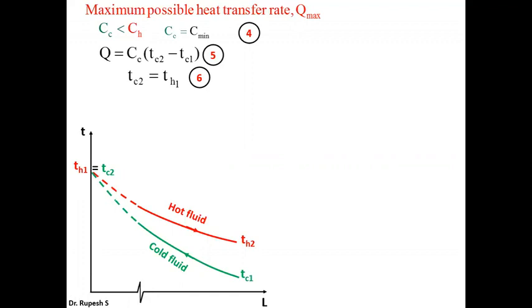So, for maximum heat transfer rate, that is for a heat exchanger with the infinite length, Q becomes Qmax when Tc2 becomes Th1. So maximum heat transfer rate can be represented as Qmax is equal to Cc. Instead of Cc, we write C minimum. So Qmax is equal to C minimum into, instead of Tc2, we will put Th1. So Qmax is equal to C minimum into Th1 minus Tc1. This is the expression for maximum possible heat transfer rate.